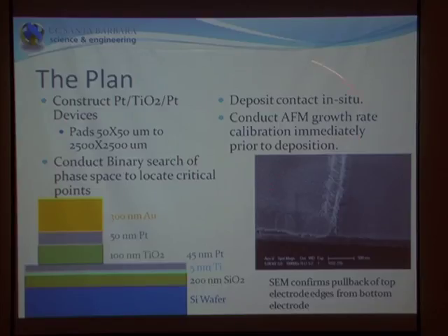I conduct AFM calibrations immediately prior to growth, and that's primarily because I do my platinum deposition in situ at room temperature. And I checked for edge effects because I had to do liftoff, and basically you have rabbit ears, and you have pull away of the top electrode from the film. So edge effects shouldn't be too serious a concern, but they might be there.